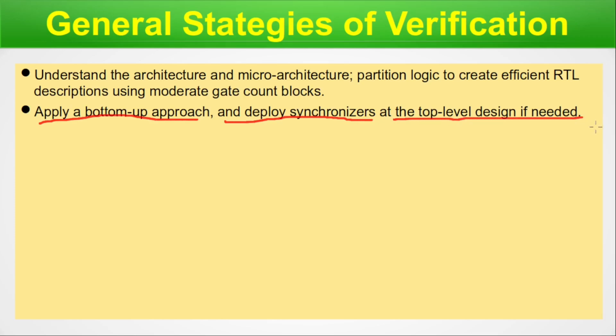I have already discussed the V-curve of VLSI. Generally, there is a specification, and from that we descend down and have a block level design. So verification happens at the block level first, and then it goes up to the SoC level. So the verification happens in multiple stages. With this bottom-up approach, we deploy the synchronizers at the top level of the design if needed. This is one of the very key things to remember.